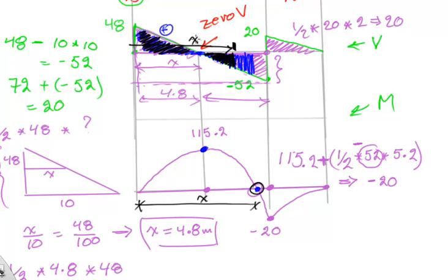So now I have a shear diagram that if I can find the area, or in other words, this small distance, and then I calculate the area and find it equal to the previous area, then I'll be able to say that whatever is before equals whatever is after, so the summation should be 0 here for the moments. Then this distance x, or this point, has the 0 moment.